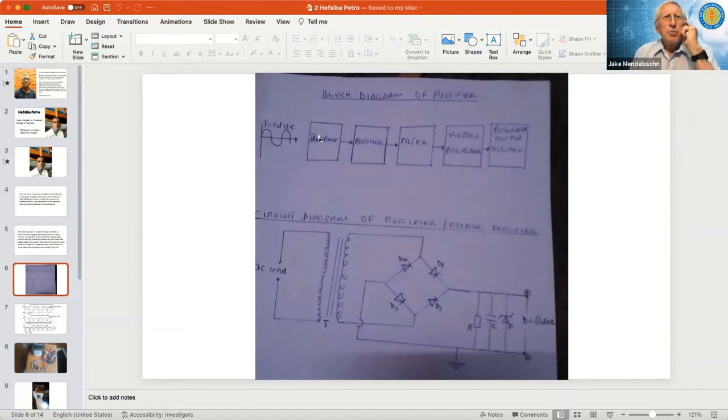And it's probably at a higher voltage, 110 volts in the United States, probably 220 or 240 in other countries. And they have a transformer that brings it down to a lower voltage. It's a little bit safer. Then the rectifier straightens it out. Instead of going back and forth, it only goes in one direction. And then you have a filter, which smooths it out, and then you maintain a proper voltage.